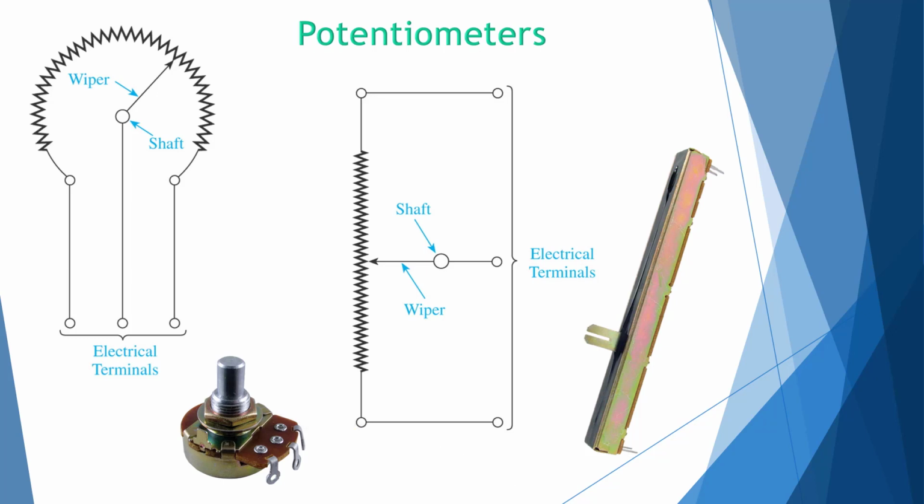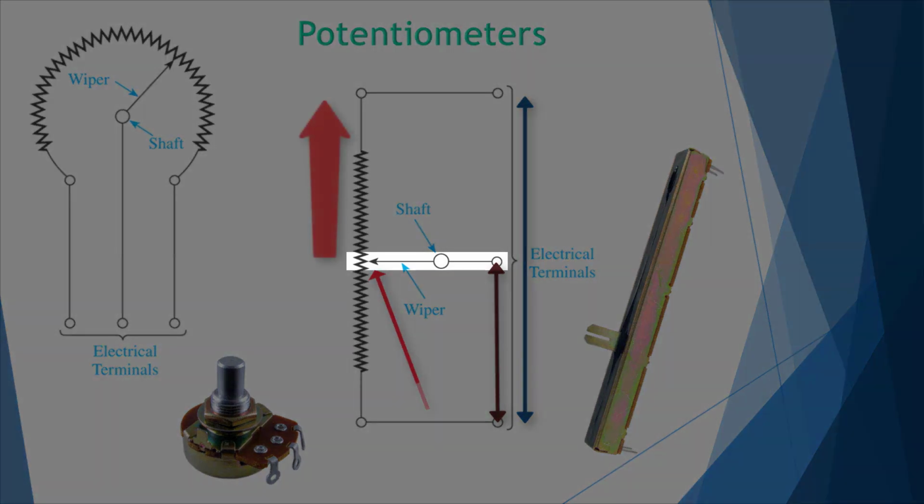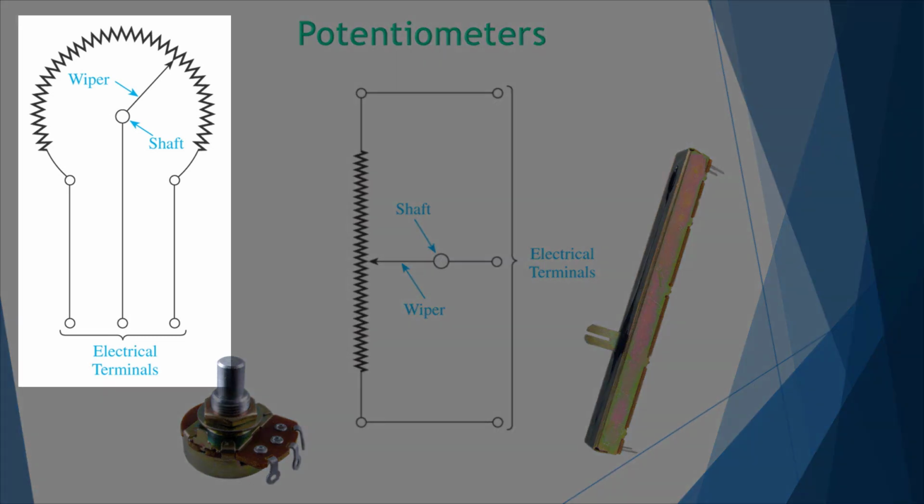If we talked about variable resistors before, we can see that if I have a voltage from here to here, this acts like a voltage divider, and the voltage between here and here will increase as this goes in this direction. In this case, the same similar thing, I have a voltage divider, so whatever my voltage is from here to here, this will tap off of that. If it's in the middle, then half of the total voltage is here to here. If this is down to 25% of this resistor, then 25% of the voltage is here.